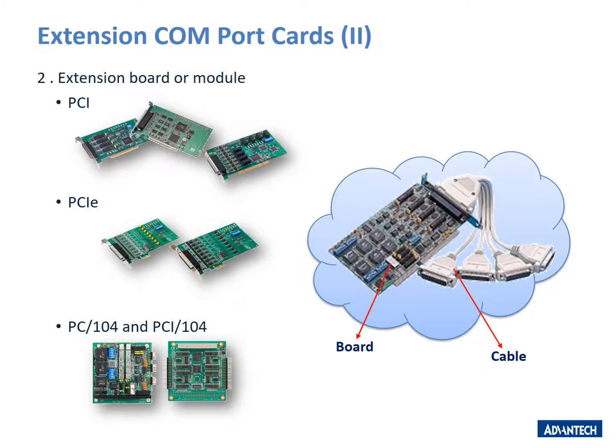The extension COM port cards are also used to increase the number of COM ports in a computer. Extension serial interface has multi-type and flexibility. It can insert into an industrial PC or normal PC. There are different interfaces of serial extension card: PCI, PCI Express, PC104, PCI104, or USB. These serial extension cards require the installation of drivers and the use of additional cable.